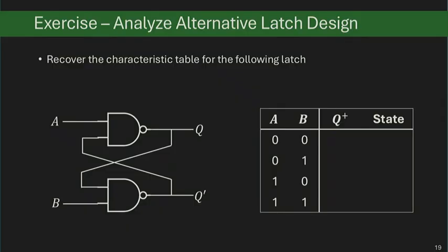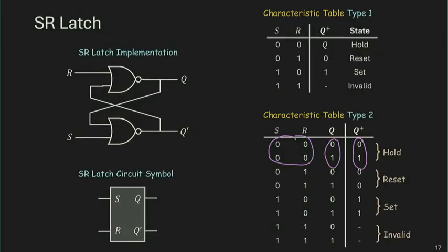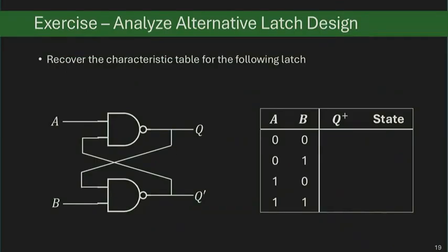All right, time's up. So you see, I showed you two different ways of representing the characteristic table, a more compact way and a more expanded way. In general, I like to use the compact table by not putting the previous state as one of the input columns. That reduces the amount of work. With this compact table, there are only 4 cases I need to try. So that's trick number 1, to try to minimize your work.